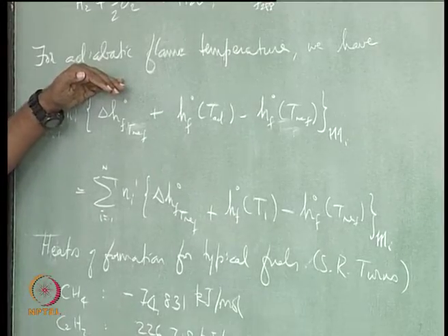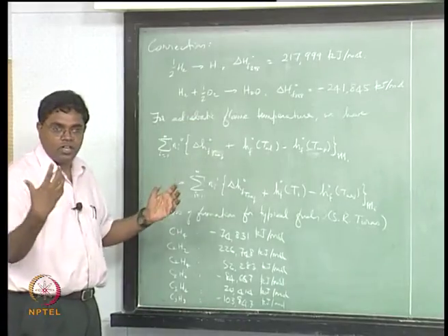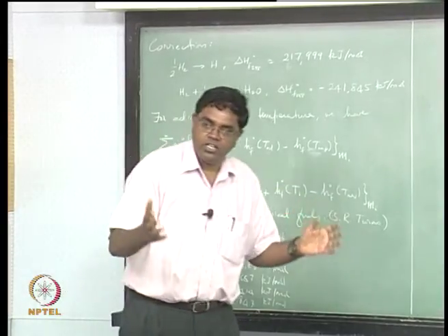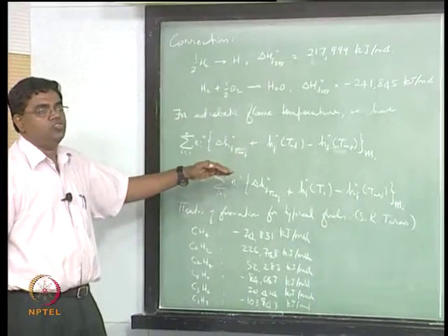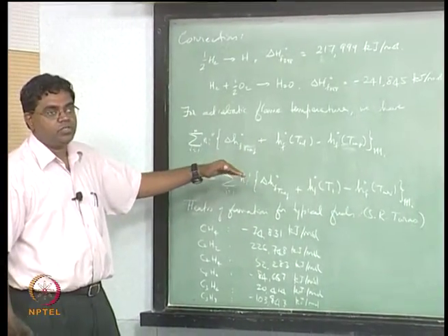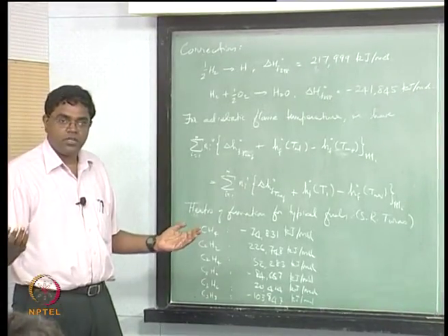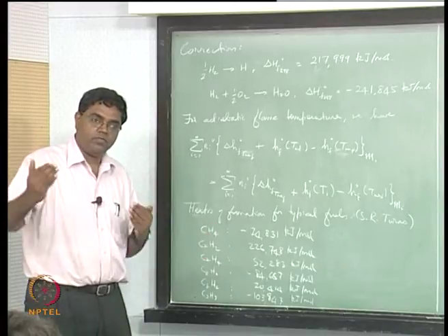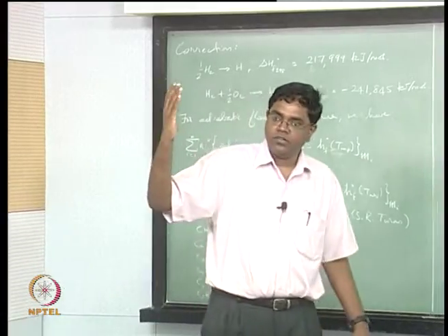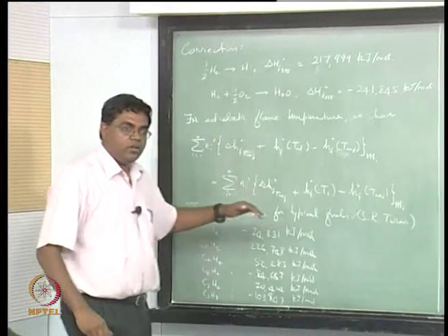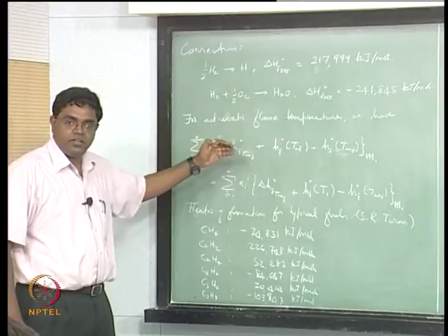In the core of the combustion process, let's say in a rocket engine or a gas turbine engine, you get temperatures pretty close to the adiabatic flame temperature, within let's say 100 degrees, which is not a lot of deviation when you are looking at something like 2500. So we are not talking about heat loss as a non-adiabatic situation.